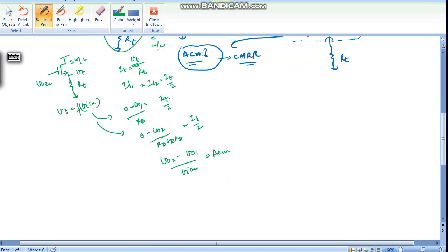So this is a source follower, and from here if we see the resistance, from here to here it will be 1 by GM of this device. So this device GM will not be only GM, because we are taking width 2 times, so it will be 2 GM.